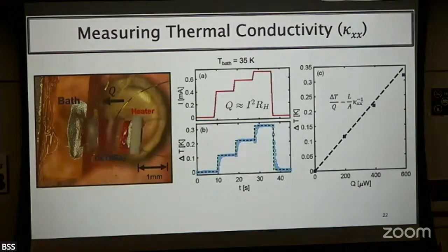Yes, right. How do you do that for temperature? We don't do that. We just do it on the DC. So this is all DC current. But even if you apply AC current, you won't be able to. If we do the AC current, we'll just see the transient behavior because of equilibrium. We want to measure thermal conductivity when the divergence of the heat current is zero, right? Heat current is always there, but divergence has to be zero. So all that comes in has to come out.